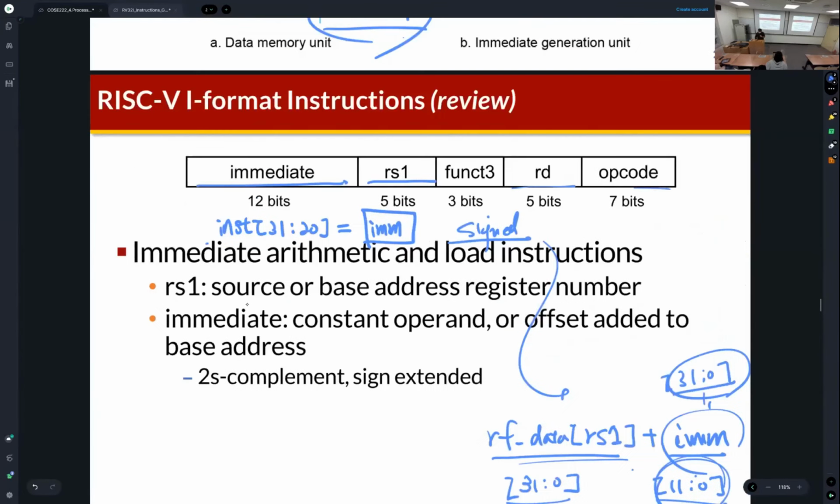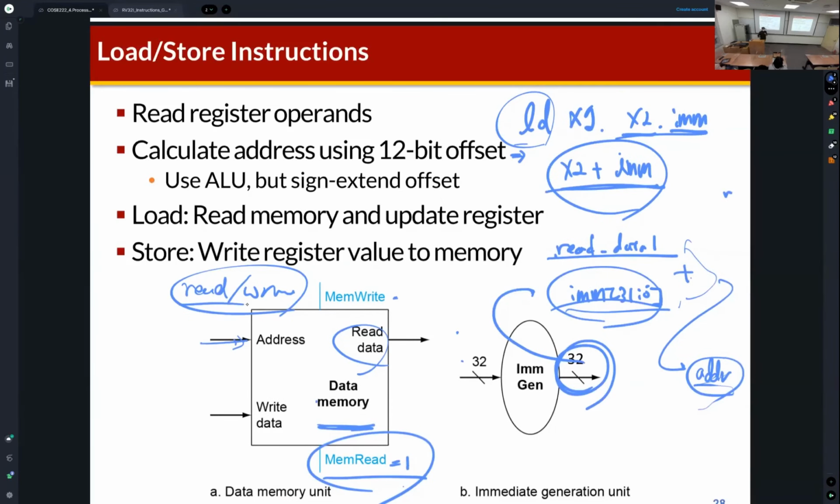Yeah, that's a very good question. Actually, in the register file, we have only one control signal called read write. But in this case, we have two control signals, mem write and mem read. It's okay. It's not a problem if we use only one control signal, like mem write, because we can just distinguish load word and store word, the load and store instruction. So it's the same.